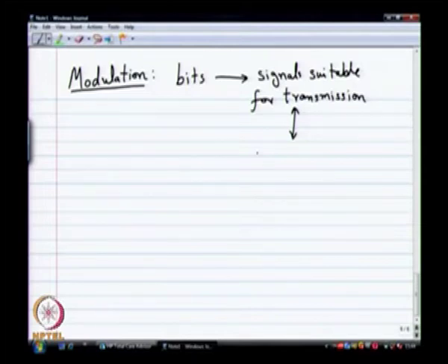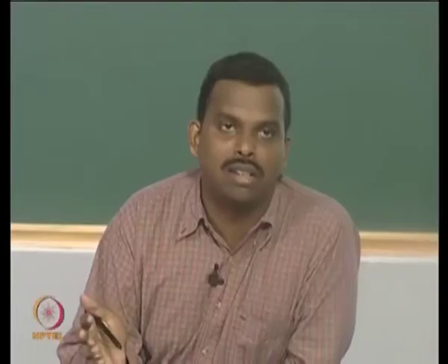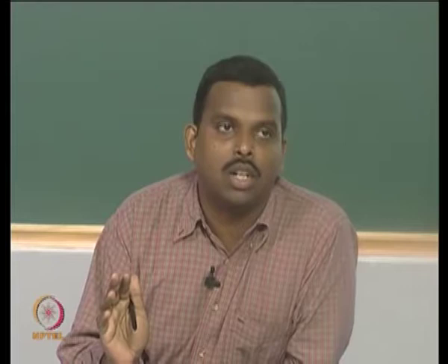We know that you can make an orthogonal, orthonormal basis for the signals, and then express your signals in terms of those bases. So you will get a point in the constellation, so to speak, for the signal. Instead of thinking of the whole signal, we will simply think of a point in a constellation, and in fact we will mostly use only a 1-dimensional constellation.